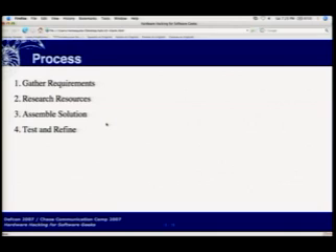But they're also the functional requirements of your device. Like this one, the requirements are user programmable, moddable, and display text on a bunch of LEDs. So it does all that. But generally this process is iterative. If you see a board that's got rev and then a number after it, that's how many times they've done a different release of that board. Usually companies start with special revision numbers so they don't have to tell anyone how many revs they went through before it worked.